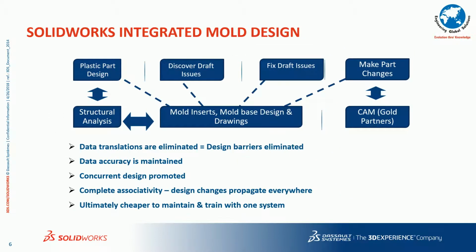So what does SolidWorks integrated mold design give you in terms of productivity? Once you make the design, find the draft issues, fix them, and create the drawings, if any design change comes, you can switch over to any step concurrently. You don't need to start again from a new design.